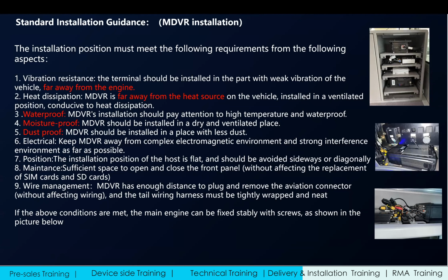Second one is that with vertical installation, some inside sensors cannot be used, like a drain sensor. And for maintenance and wire management, we need to make sure the installation location for the rear side makes it easy to find the cable and do the replacement and maintenance.